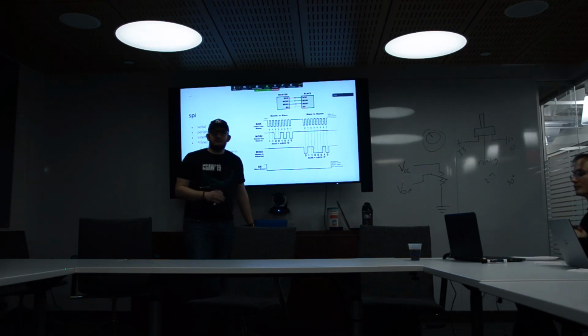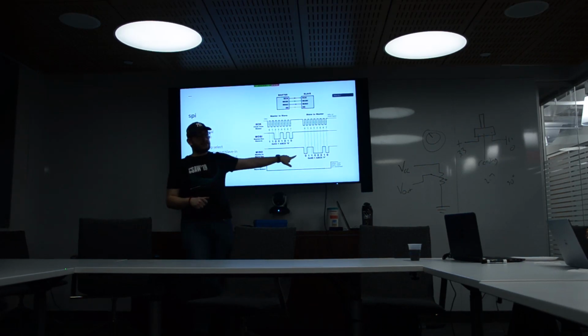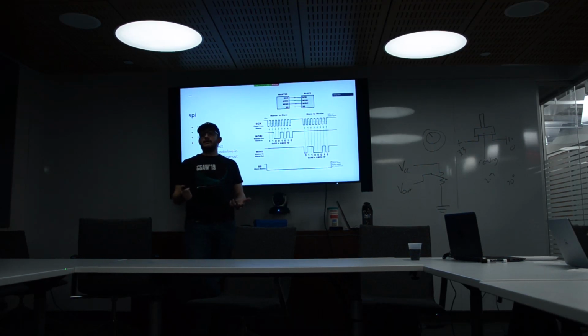Specifically for sensing, there's almost never any. Flash chips, interestingly, a lot of them speak SPI, and this is how you interface with them. If they don't explicitly have a secure mode or an encrypted mode, you are literally just shoving bytes back and forth over that with no protection. That's why buses are so vitally important to hardware hacking.